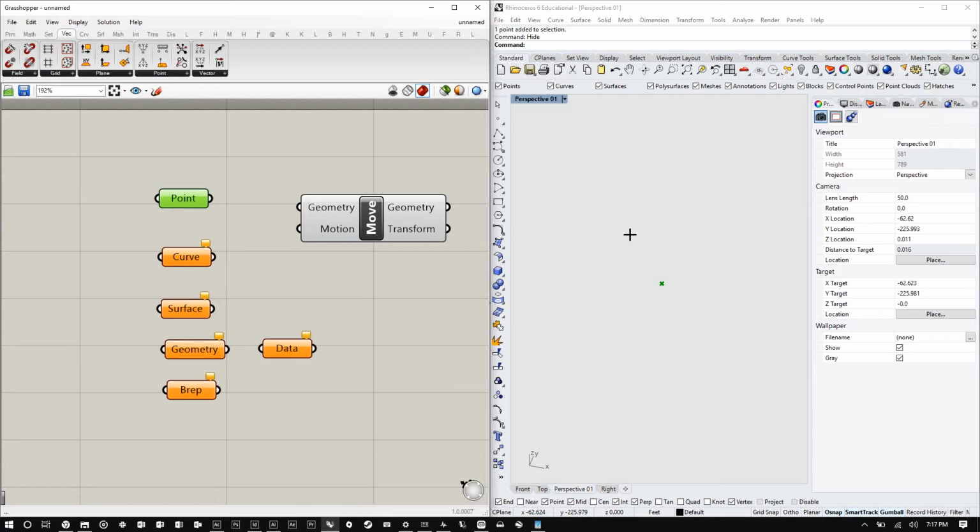What it's doing is referencing the Rhino geometry inside Grasshopper. Yeah, I understand that. I just, that didn't happen on my screen, but that's okay. What happened? Well, I don't see the point that I referenced in Grasshopper. Is a command running, like select point inside? Look at Rhino. Is there a command that's running?